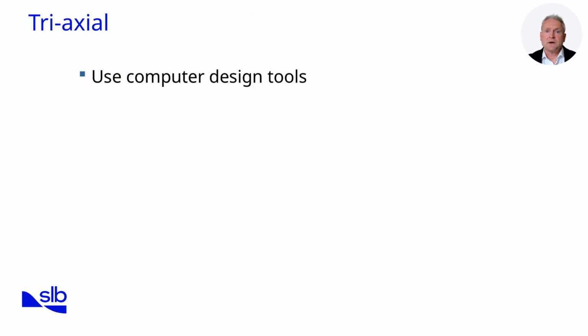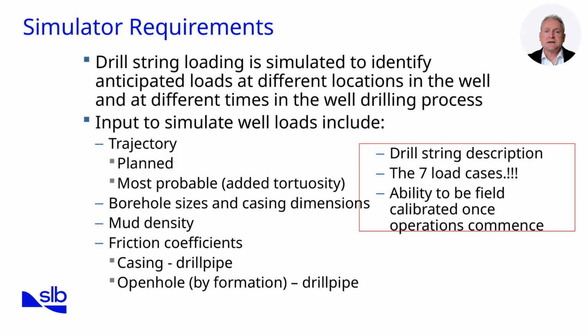Triaxial design requires somewhat complex algebra calculations and can be performed by hand or coded into a spreadsheet. However, to perform an analysis for multiple locations, it is much more effective to perform the analysis with a software program. Simulators allow us to model how the drill string will behave under the 7 key load cases defined by DS1: tripping in and out, rotary drilling, reaming, back reaming, slide drilling, and rotating off bottom.